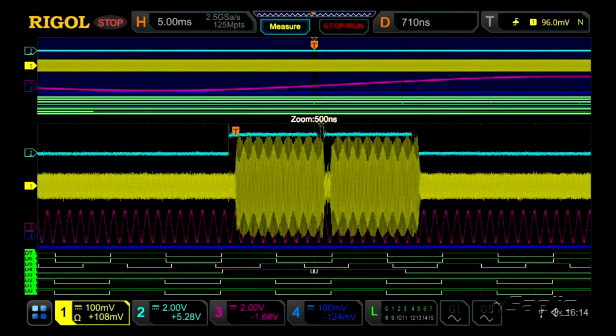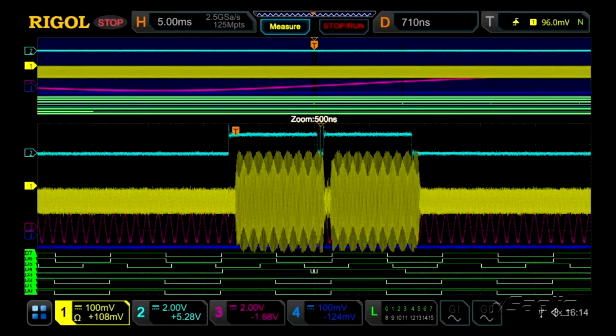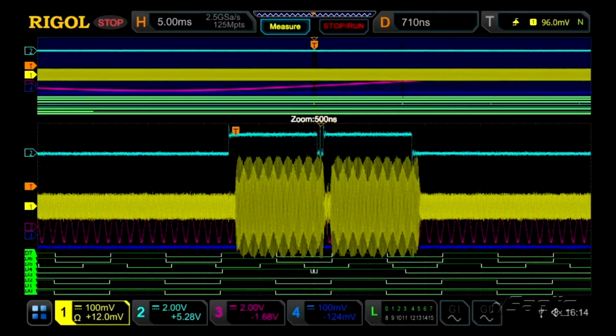Now we can identify the activity. We can even identify some other signals, like channel 2 in blue and D4 down at the bottom, that appear to be related to this pulse activity and the glitch in the middle of this pulse. So this mode really allows us to see the same full 50 milliseconds of time with 5x oversampling on all our channels, but capture the signal in context and use the memory in a more flexible way to get all the information we need.